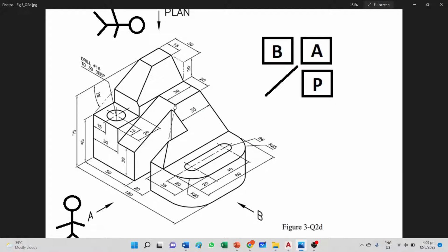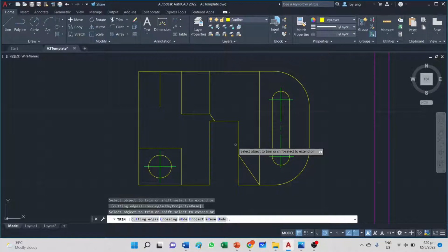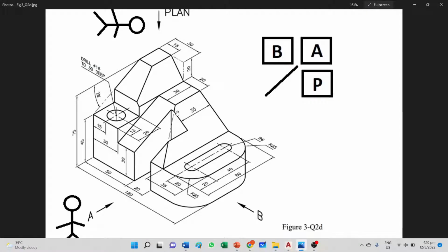From this corner, there is a line that goes all the way down to this corner because of the chamfer. So you need to recognize the corners. And from there, it's actually this corner all the way to this corner here. So you can confidently draw a line that cuts across. Then what we do is we trim this away. And we have this shape, okay, which is shown here. Alright, we have this shape that's shown there.